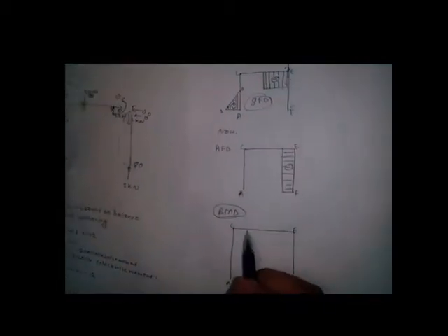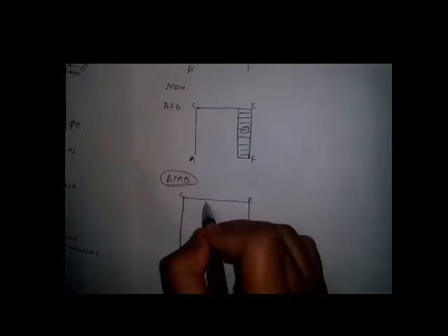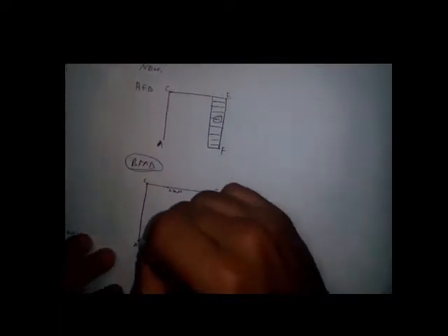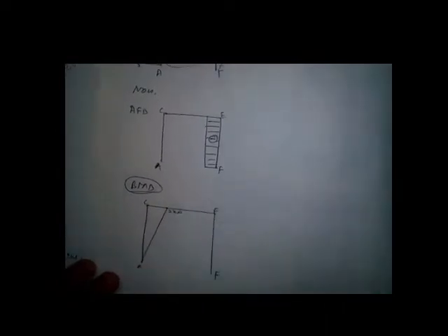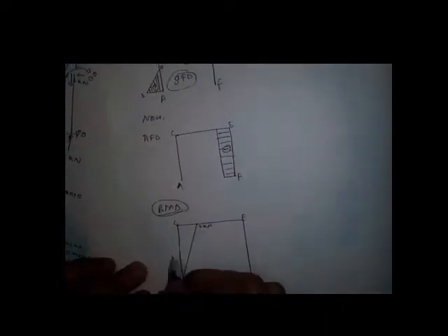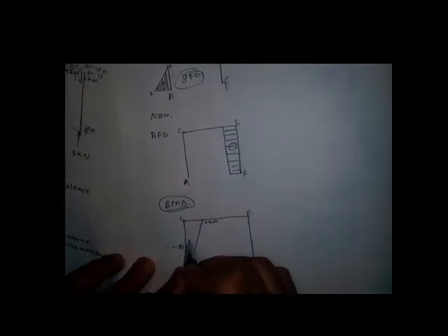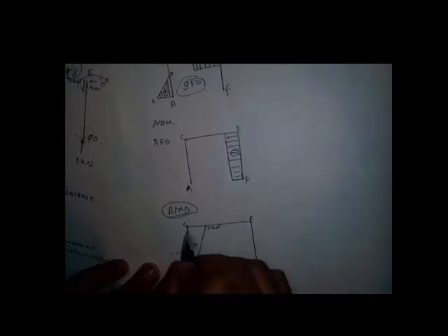So here is 0. And at point C, you see the bending moment is 2 kilonewton meter and it's anti-clockwise. Anti-clockwise, we need to plot inside. So here comes 2 kilonewton. And you just join the member with this, and 2 meter. Here will be B, and here is the load, and it's anti-clockwise, so we assume anti-clockwise as a negative moment, and hatching the same way perpendicular to the axis.